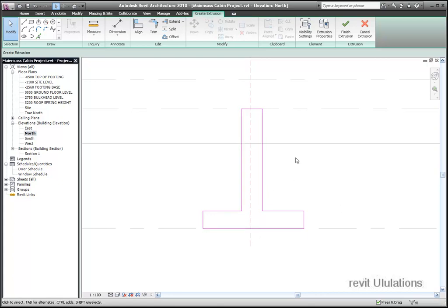Yep, I'll do that again. So I select the line I'd like to move. I go and change the witness line also. I adjust the witness line. So drag it to the middle reference plane and change it from 200 to 150. You might have a different dimension on yours, but that's what you would do. I've got the horizontal part of the inverted T at 300, which is what I want, so that's fine.